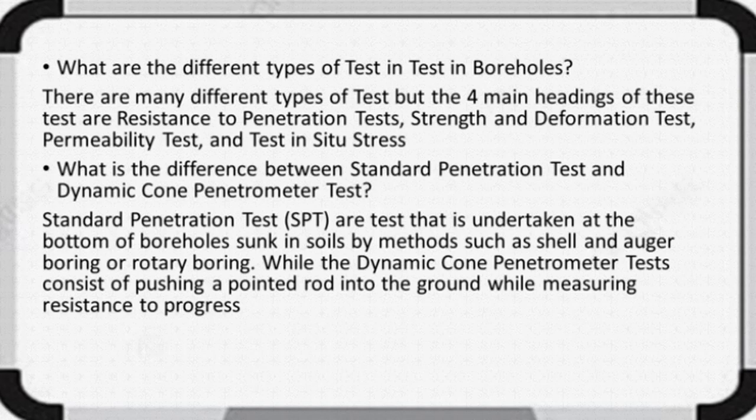Number 4: what is the difference between the standard penetration test and the dynamic cone penetrometer test? The standard penetration test, or SPT, is undertaken at the bottom of boreholes sunk in soils by methods such as shell and auger boring or rotary boring, whereas the dynamic cone penetrometer test consists of pushing a pointed rod into the ground while measuring resistance to progress.